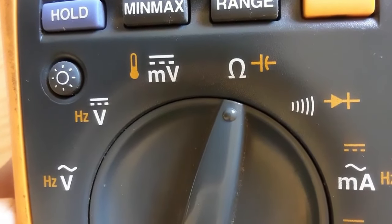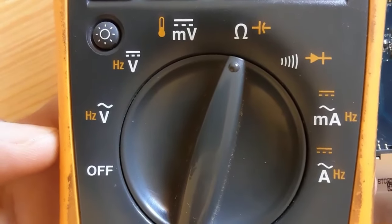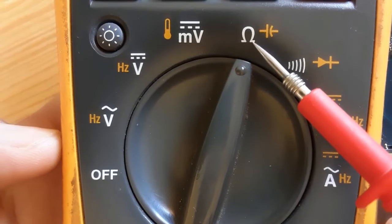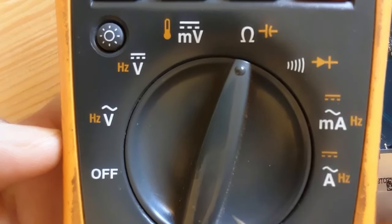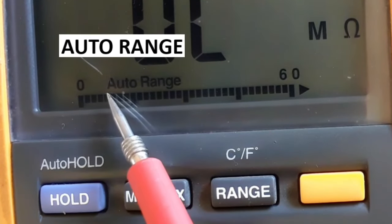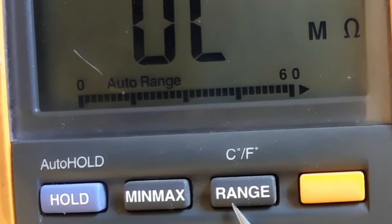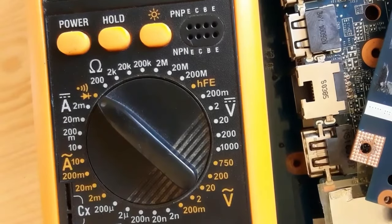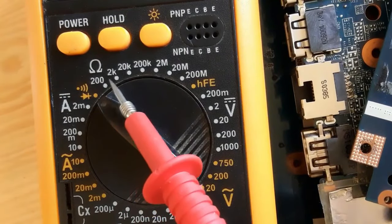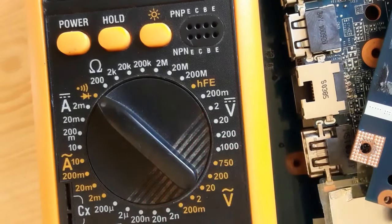So in this lecture I'm going to show you how to test all types of SMD resistors using the multimeter. Of course we're gonna select the resistance option or the ohm option on the multimeter. As you can see here we have the auto range, so this is an auto range digital multimeter. Of course you can also use this kind of multimeter where we have scales and gradation, and you can choose any scale you want.